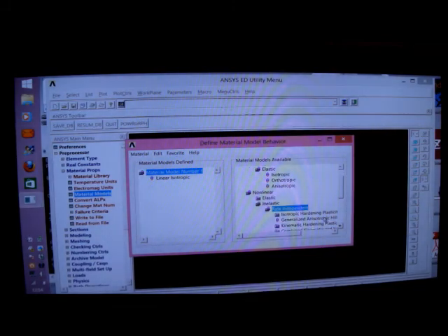non-linear bit. I'll go for non-linear, inelastic, rate independent, isotropic hardening, Mises plasticity, bilinear, and this yield stress is 250 megapascal, that's reasonable for mild steel. And the tangent modulus, I'll make the 100th of the Young's modulus, so it's 2E3, it's fine, and that, okay, and we come out of this, and we put